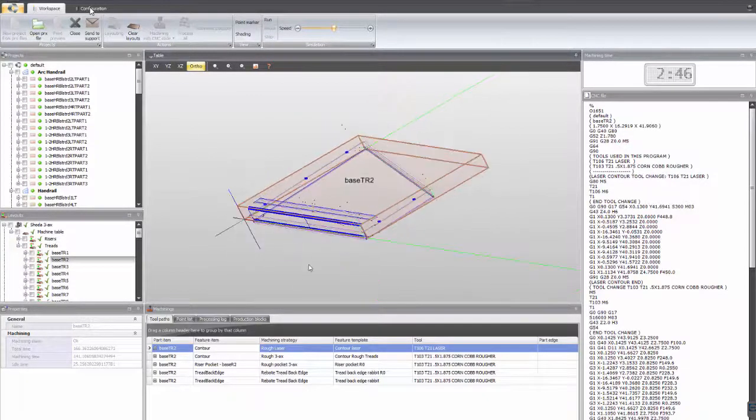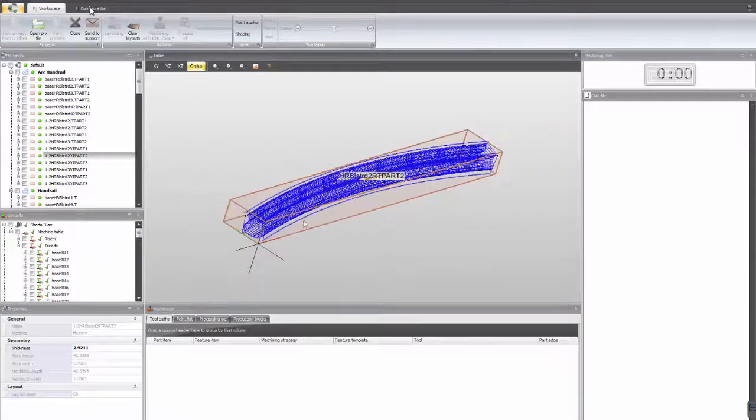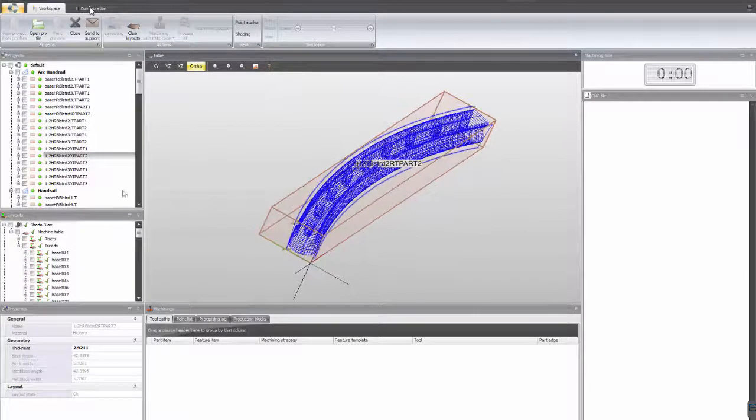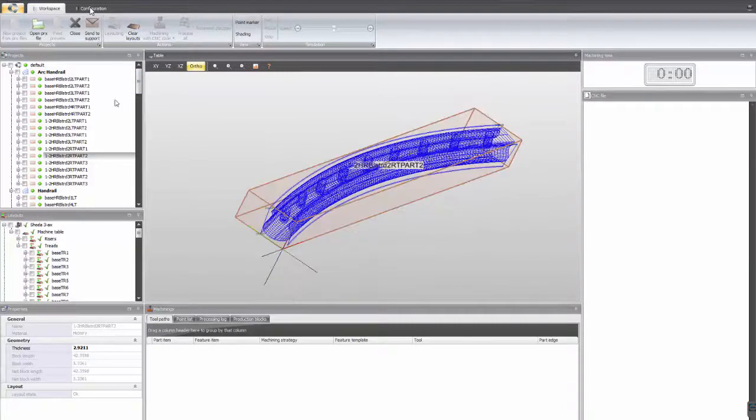So you're able to run a bunch of different styles of profile, whatever you've got or that you typically do. It's all able to be edited in the configuration for CAM. It also goes with handrail. We run a lot of different styles of handrail. And the profile can be easily added into the database and machined in whatever profile you have, and you change the settings to work. It can also be changed so it can be plowed out for fillet or drilled for balusters, different size holes, whatever you need to do. It's all very editable and customizable as you need.